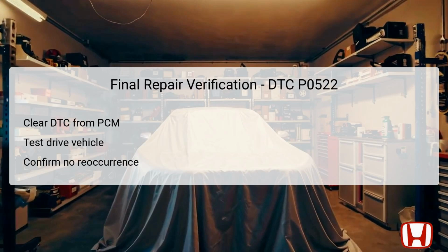After addressing the underlying issues associated with DTC P0522, conducting a final repair verification is essential to ensure that the corrections have been successful. This verification begins by clearing the DTC from the PCM using an appropriate diagnostic tool. Once cleared, it's beneficial to take the vehicle on a short test drive, during which the operation of the engine and related systems can be observed under real-world conditions.